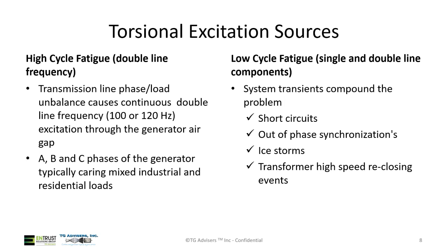Did you evaluate based on calculations or analysis that has a wider margin of error, and then by testing, there's a narrower margin of error. So you figure out your whole rotor train and you say, all right, I'm in the good or the bad zone or the intermediate zone, and depending on where you're at is how you'll treat that during the design process. And that's important. I'll talk about in the next slide when to be concerned about torsional vibration on units.